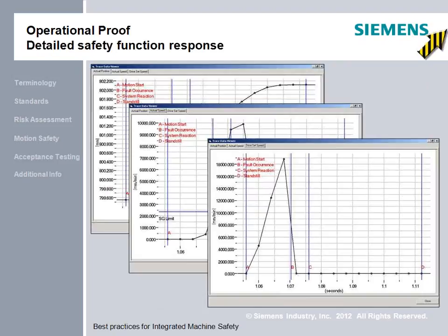As part of any acceptance procedure is the documentation, and I have this slide here just to indicate the type of charts and graphs and documentation you'll see. In this case, the classic 3 charts that indicate the response to a failure condition. In this particular case, it could have been that 1 meter per minute velocity that I had configured maximum with the door open. During our testing, we will violate that 1 meter per minute and record, graph, chart, document the response of the safety system. So this is a very quick example of such an implementation.